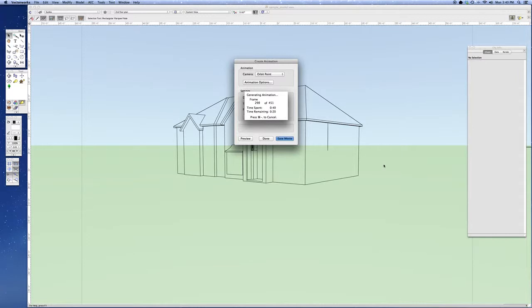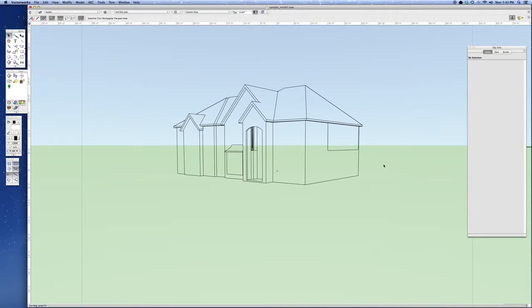The more layers of details we add, notes and lines and polygons and dimensions, and even starting to place fixtures or cabinets or plumbing or those kinds of things, if the layout changes, that just means that all of those items need to be changed and moved and shifted around. So the lighter we keep the details at the beginning while we're getting the design and the 3D look just right, the less things we have to fool with while we're doing those edits and going back and forth with the actual design phase.